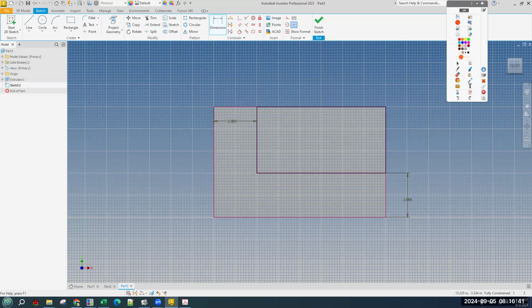I'm showing you. Instead of making the size of the rectangle, we are dimensioning the size of the remainder, which is the same thing in this case. So with the dimension tool, first click is on this line. Second click is on the side of everything, like the side of your main shape. And the third click is in between. Just in the middle here is fine. Yep. Set that to 2.